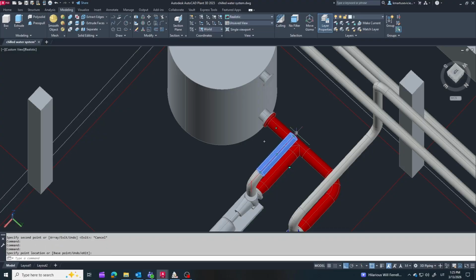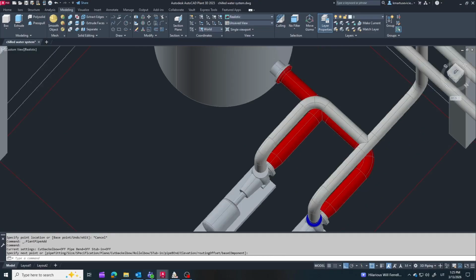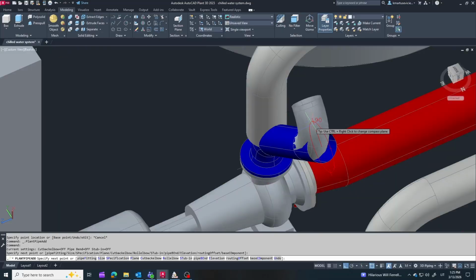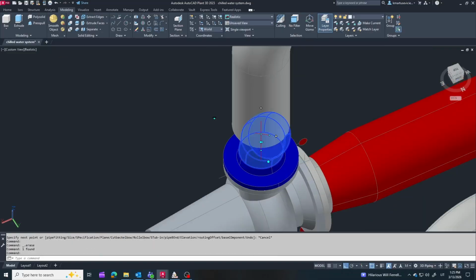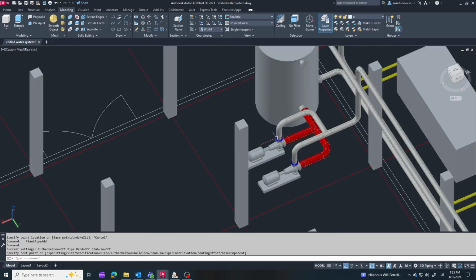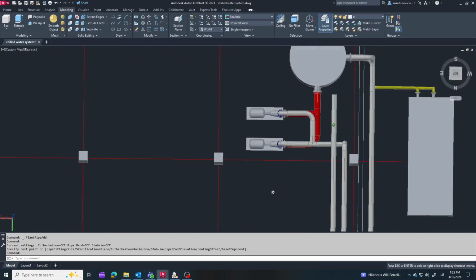I also like to arrange the pipes one above another. It makes the layout cleaner, the support simpler, and the whole piping system easier to understand. I try to avoid strange angles and unnecessary turns, so the routing stays ordered and more practical to build.